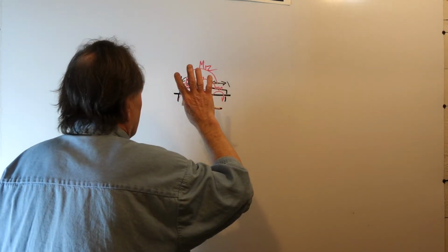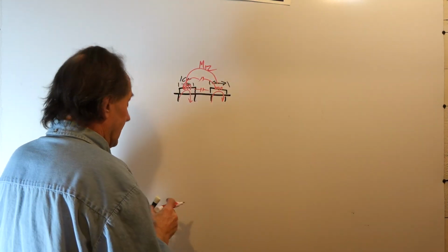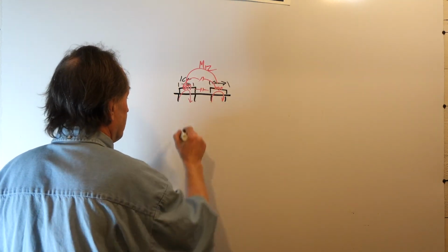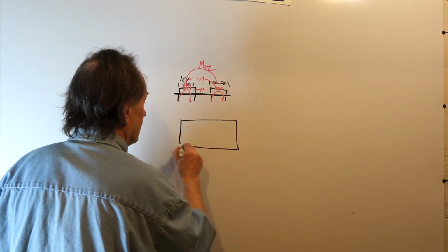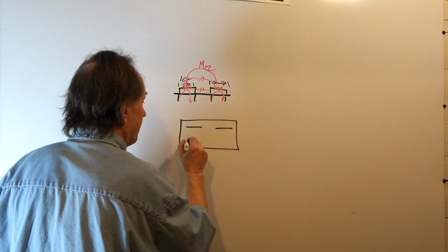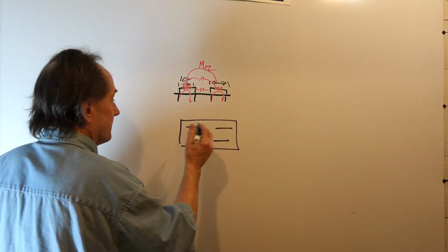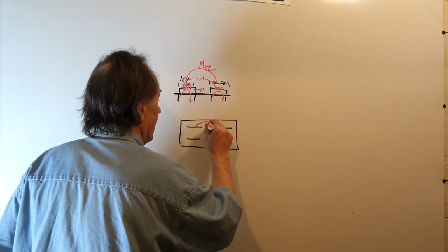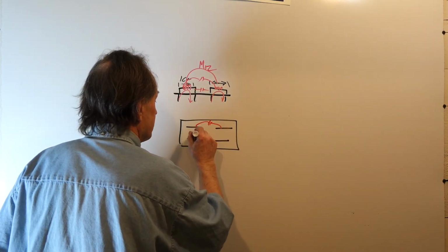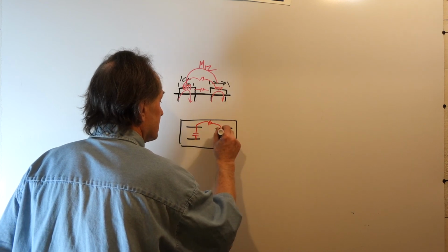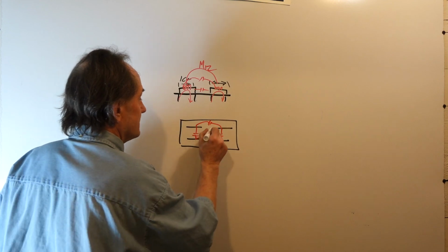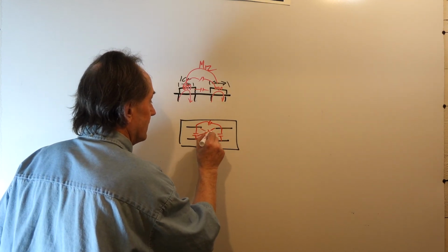So nothing's ideal in this world of sub-parts per million. If you look from the top of the relay, some of these relays, say, have 4 in a package. And so you have to worry about things like stray capacitance between each of these, mutual capacitances coupling between all these and going across this way and across this way.